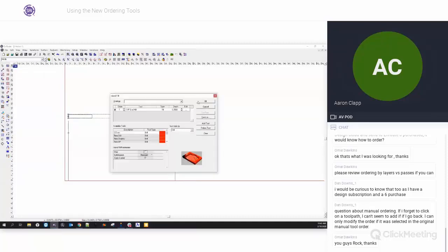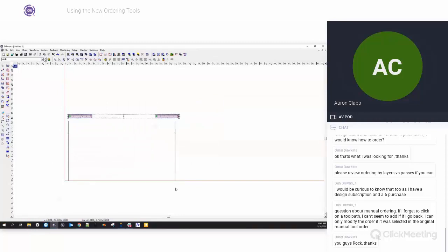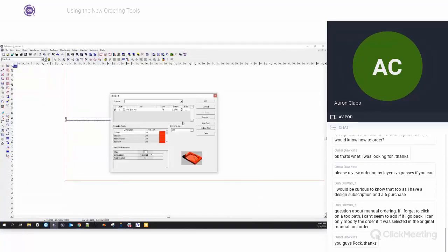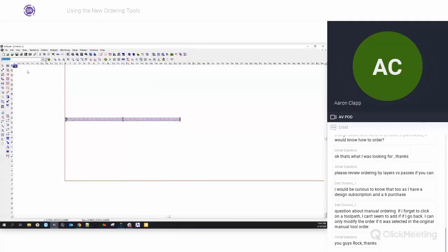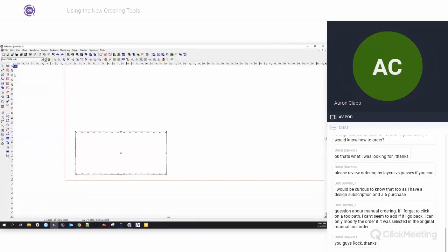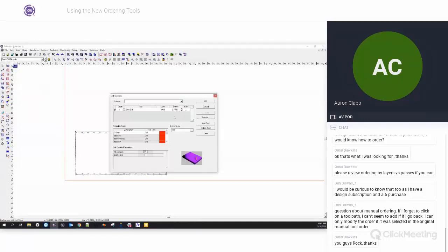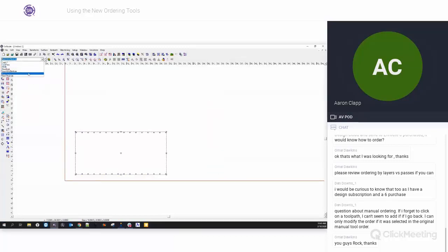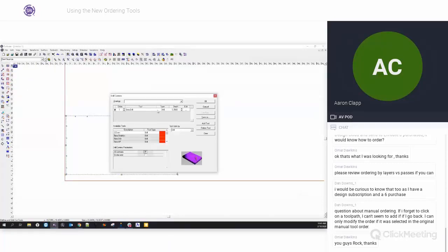So we've got a couple of these. I'm just going to throw an island fill on here. That's fine because I was kind of messing around with this earlier. These I'm going to do an engrave. Route back. This will throw an island fill on here. Again, I'm kind of doing this fairly carelessly, but we'll do some, oh, those are not, let's do those at a little different depths. Let's do those at 0.25 instead. And these are our through holes, so we'll do these at 5 millimeters all the way through.